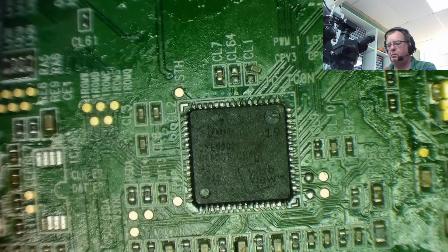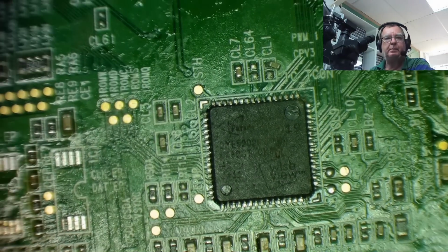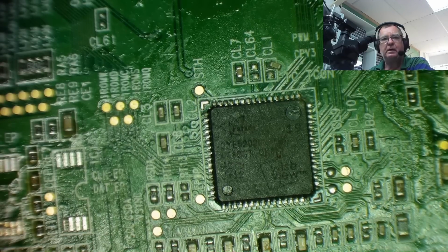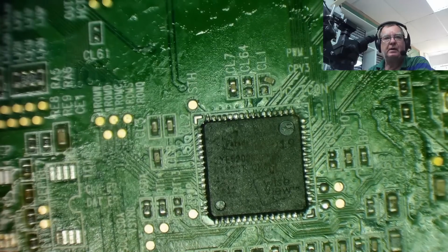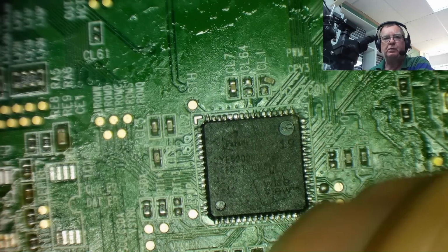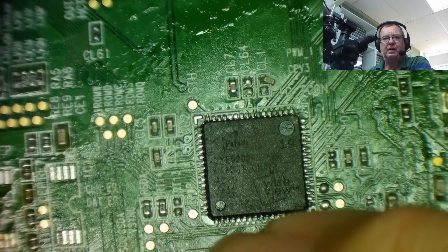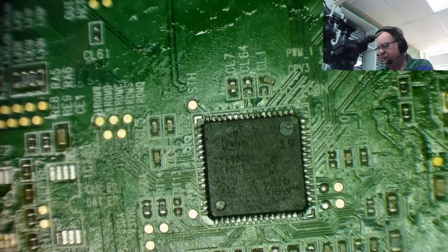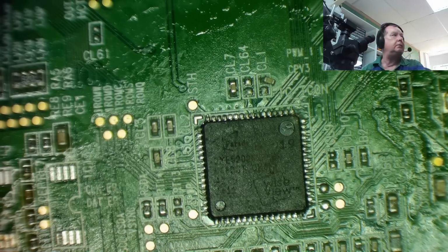Okay, so I've got the large chip back in place on the board. It may be possible to solder this with a soldering iron now, because there are small legs around the edge of it. The technique here would be to get it lined up and just tag one of the pins in one corner, then make sure it's lined up and tag pins in the opposite corner. Once you've got the two corners down, you can then run around the chip and solder it, basically.